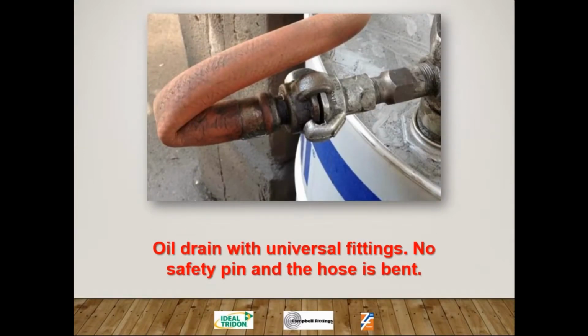And here's another kind of typical hookup. You have a really tough bend on that hose. You have a banded hose and you have no locking pin. So at this point, if you're walking around this plant with the maintenance manager or whoever it may be, now comes a discussion of, okay, you don't have any pins in your fittings. I can help you with that.